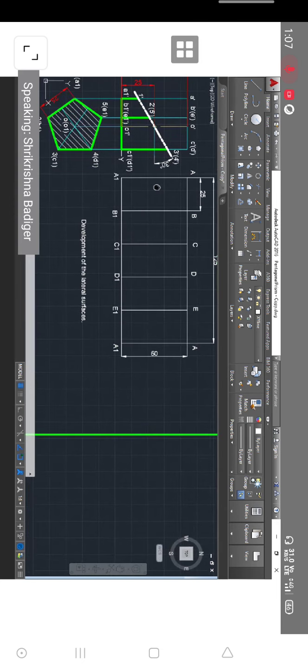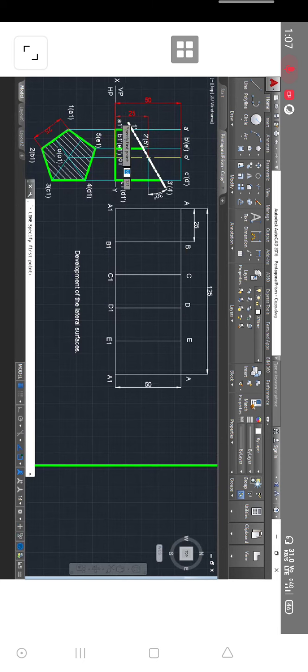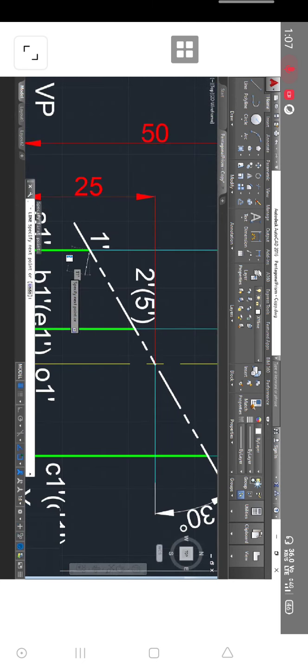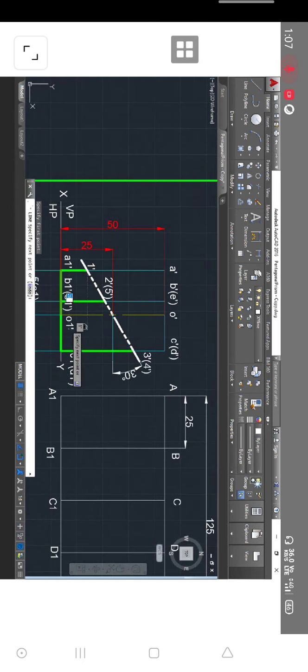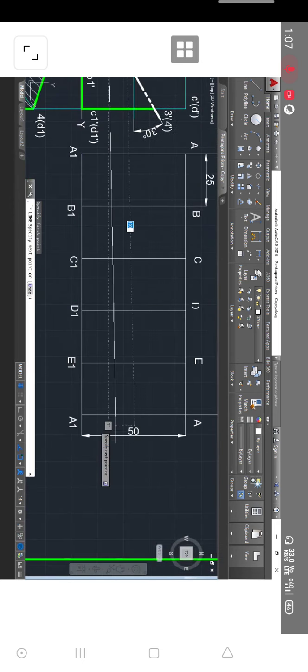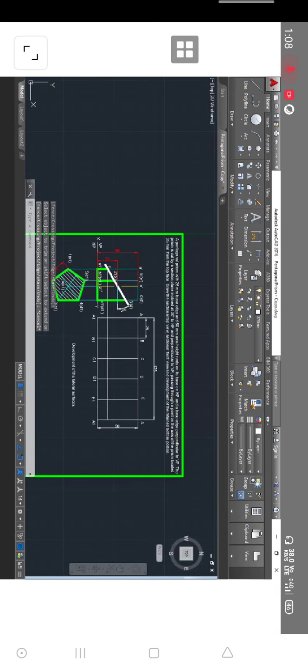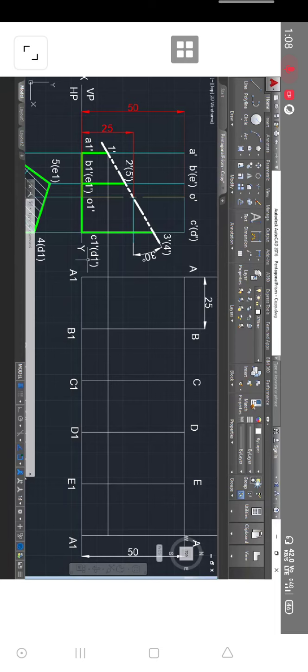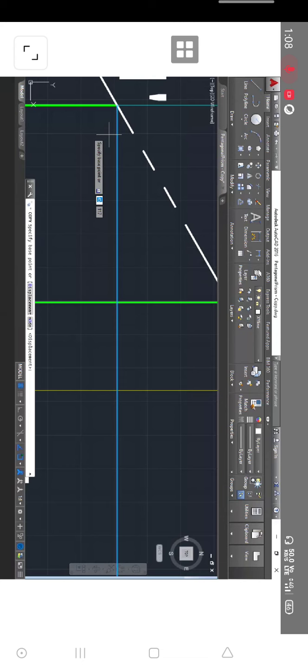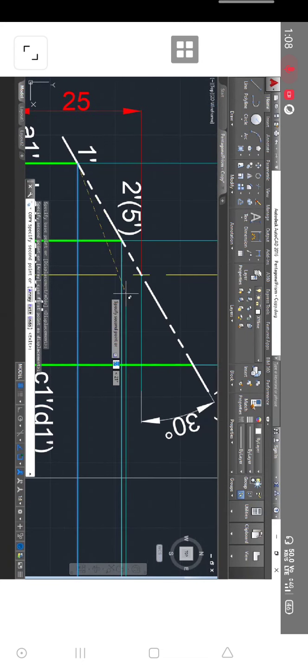So to get point one, what I have to do is start from here, travel horizontally, length may be whatever, angle keep it 0. Then you trim up to A1, because 1 is up to A1, and you use this and copy it from here to here and here.